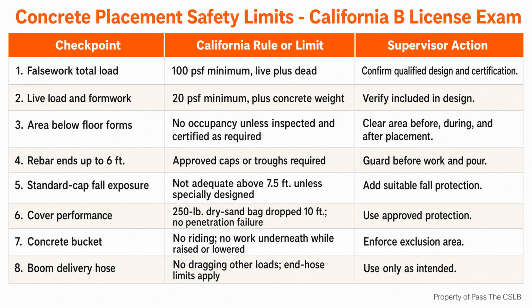Exposed, reinforcing steel ends up to 6 feet above grade need approved protective covers or troughs. Standard caps are not adequate for a fall exposure greater than 7 1/2 feet, unless they are specially designed for that greater impact. Approved impalement covers must withstand a 250-pound bag of dry sand dropped from 10 feet without penetration failure. Nobody rides a concrete bucket, and nobody works beneath a bucket while it is being raised or lowered.